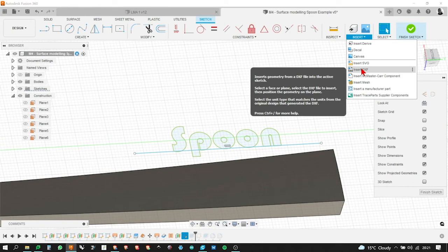Exactly. What I tend to do in Illustrator, when saving as DXF, is often save it as an early type of DXF, because I don't understand why or how the drawing exchange format works, but sometimes there are certain things it doesn't import correctly. If you bring it back to an early DXF, like R12 or R13, then it generally does work. I have found SVGs to be quite reliable coming into Fusion. They can work quite well.